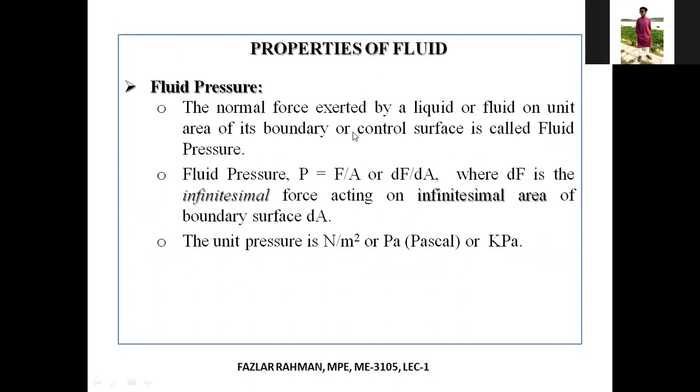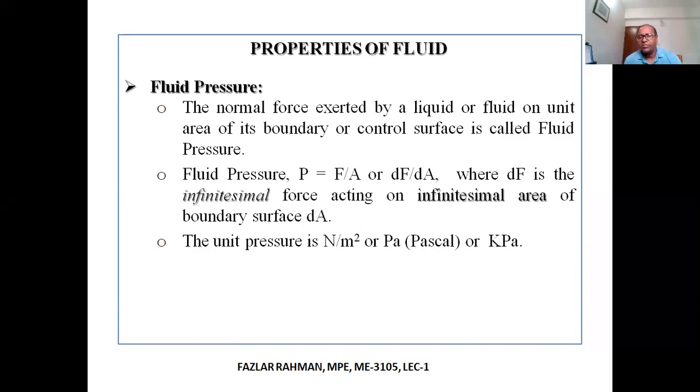Sir, can you tell us some factors that cavitation is dependent on? For example, if the fluid is denser, how much bubble will it create? Well, it depends. A lot of factors are involved there. Fluid has viscosity, capillarity, then it has a boiling point. What is the boiling point of the liquid? How much pressure is there? What is the viscosity? There are a lot of factors there. In cavitation, you can do a PhD on cavitation.